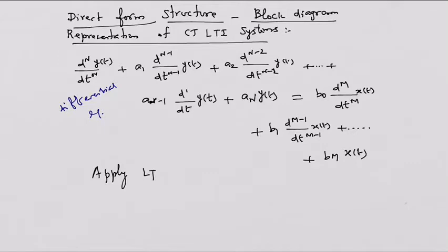So for block diagram representation of a continuous time system in time domain, the differential equations are used. Some of the block diagram representations give a direct relationship between time domain equation and S domain equation. So in that sequence, we are going to see how direct form 1 could be used for realizing a system in the form of a block diagram.